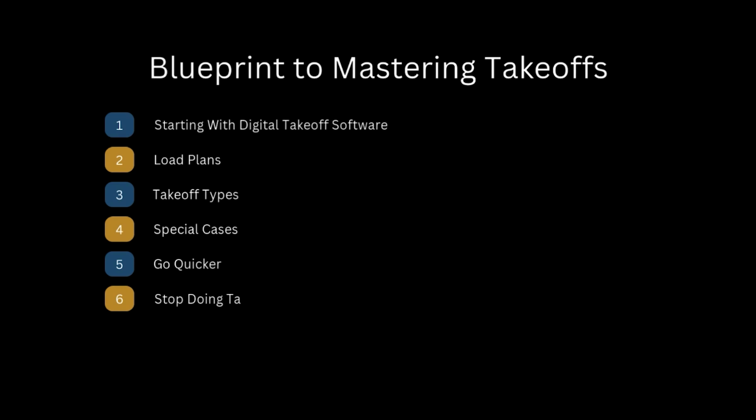All right, so now I'm moving on to number 6, which is how do you never do another takeoff ever again? The first step is doing the first 1 to 5 there and getting your system, getting trained on it, understanding it. The next thing is creating a document where you're just documenting what the process is for doing takeoffs. It doesn't have to be super built out. You can even put a link to this video, go watch this video, as part of your SOP document that you're going to create and just go through the different things: loading a set of plans, this is how you do it. Doing takeoffs, go through the template, and this is how you do a lineal. This is how you do an area. This is how you do takeoffs for concrete or framing or whatever.